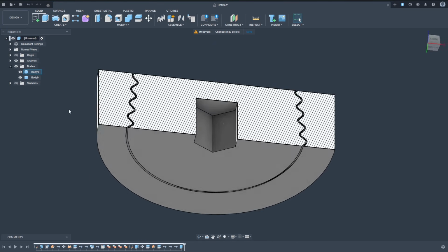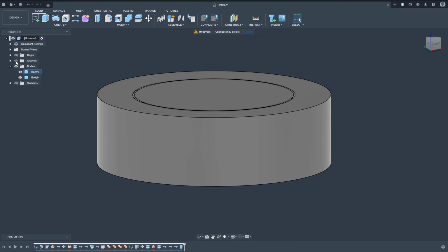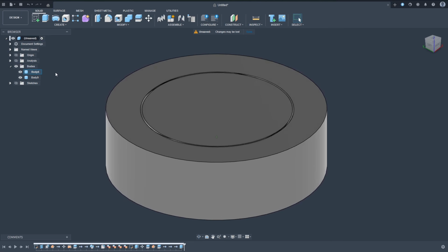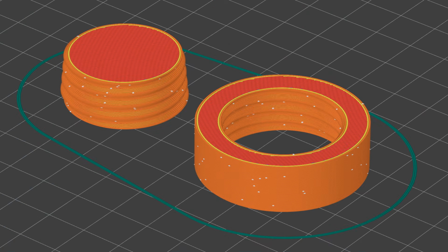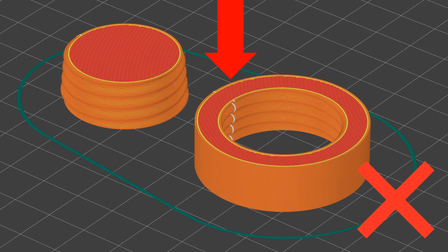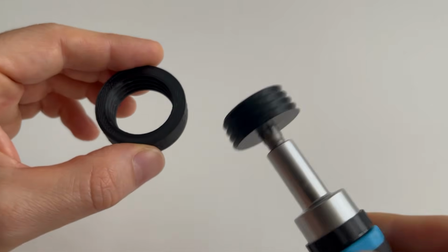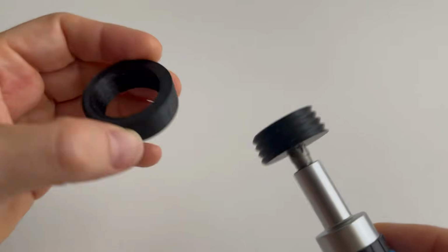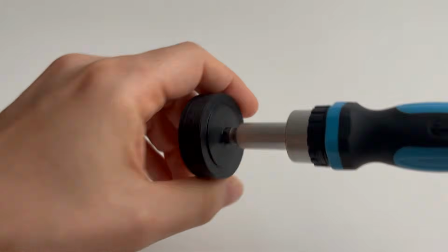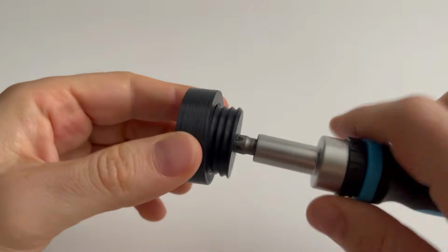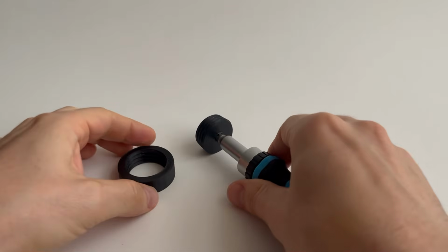As I have just recently calibrated my printer to give accurate dimensions while maintaining strong parts, which is a topic that definitely deserves its own video one day, I printed the version without any clearance. When printing threads, I always choose a random seam in this area to avoid any aligned seam stopping me when tightening. I found that I could tighten the connection to being almost flush, just to recognize that I was not able to disassemble it anymore. Only with the help of a lubricant and by forcing a larger Torx key in the center was I finally able to remove it again.